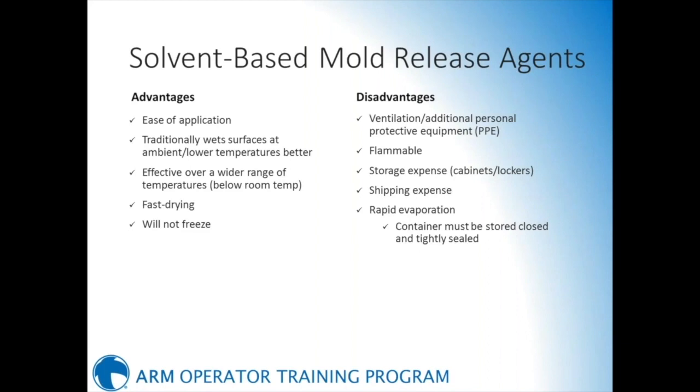Some of the disadvantages are, you need ventilation, whether it be air movement or a hood. Some additional personal protective equipment may be required. They tend to be flammable. Not all solvents are flammable. Some are combustible, but it should be treated as such.